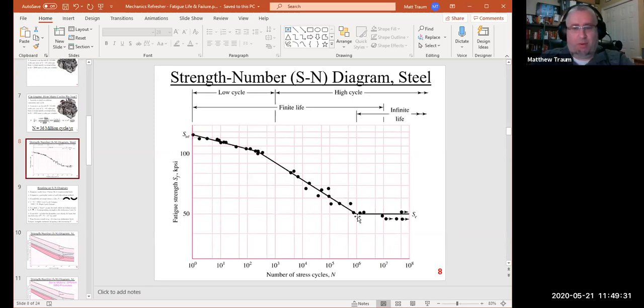So yeah, to your point, you can see here, they've obviously measured a couple of additional points just to be sure. But once you see this knee in the data, and you've taken a couple more data points just to convince yourself that your measurement's not an anomaly, then yeah, you don't need to do any more testing, provided you've got a ferrous material, provided you've got steel or a steel-like material. There's no need to test it indefinitely once you've identified where that knee is.